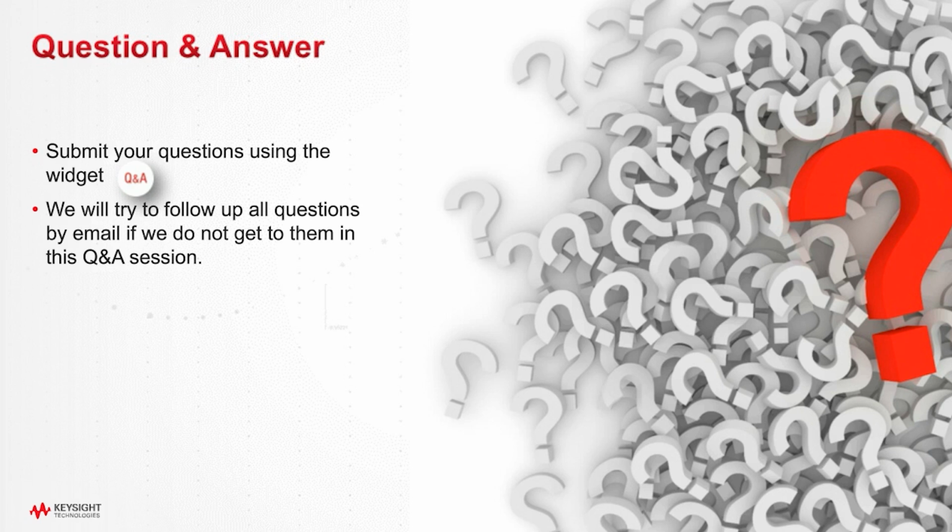Okay, thanks, Matt. Great answer. And here's one more question. Is it possible to be able to make measurements on either a wafer or a PC board? Absolutely. A lot of devices don't have connectors these days, so there's all kinds of fixtures and probes you can use to measure devices on wafers and PCBs. You will have to de-embed these fixtures from your measurements, or you can just use an automatic fixture removal software that does it for you. And so you'll be able to get the same quality of measurements on a wafer or a PCB as you would on a connectorized device.